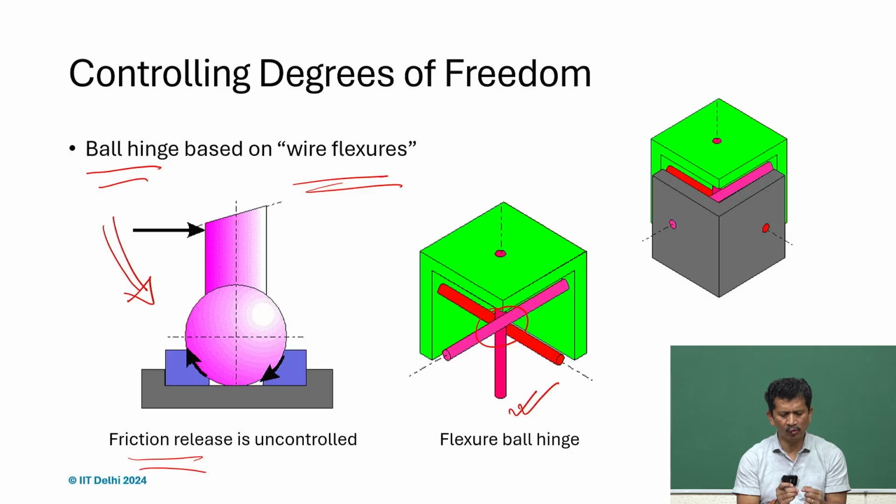So, we cannot get the exact pole, but slightly off, but for many applications it is good, and the offset we can always measure with respect to the rotation and compensate for it. This is using simple wires, maybe 1 millimeter or 0.5 millimeter steel wire with 20 or 30 millimeter length, which may be sufficient for many applications.